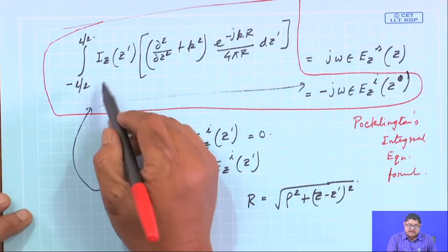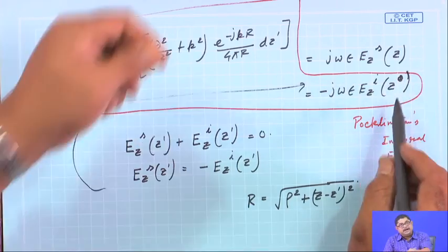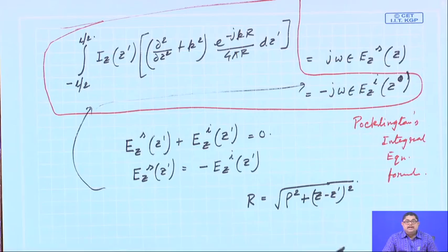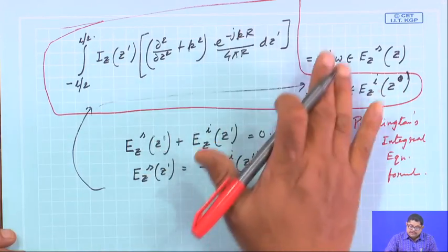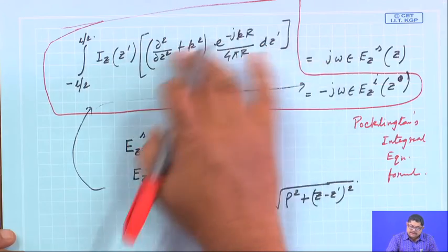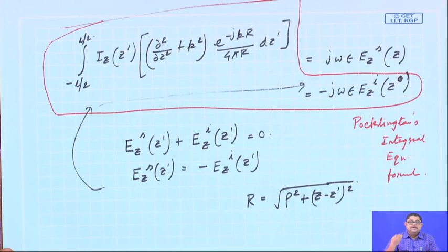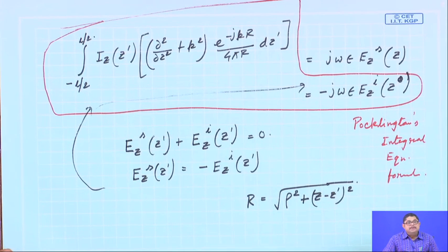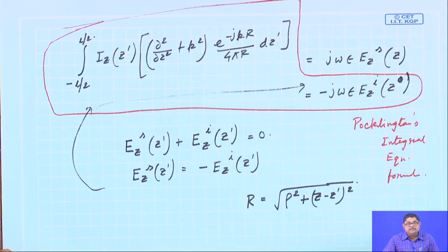You see, it is a similar structure, an integral equation, because this is unknown and this part is known. Actually, from the given excitation, the spark gap, I know what E z i is and I can calculate it. If it is any other type of feed, I can find that. So, E z is in my hand, it is known. This side is known, this side is some operation on the unknown function. So, I need to solve it. This integral equation, for both Hallen's and Pocklington's, people have solved, and there are various techniques. One that I said is most efficient and easiest for computer implementation is the moment method. We will discuss a bit of the moment method in the next class, and then we will see how to solve this equation. Thank you.